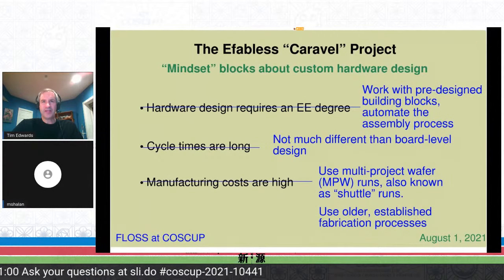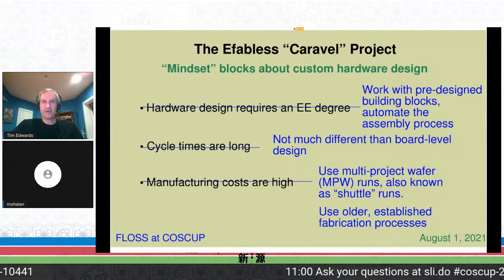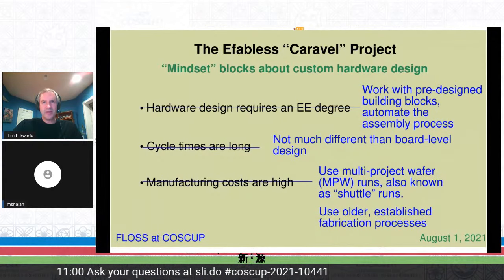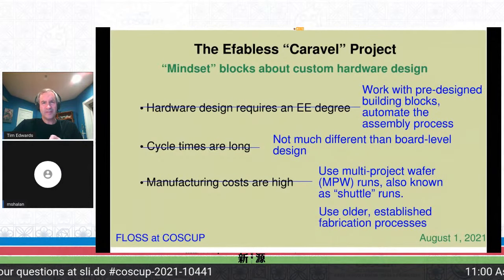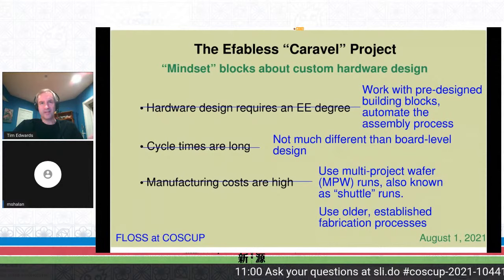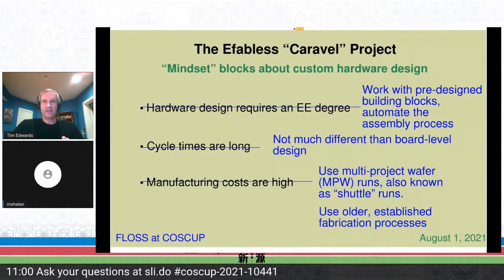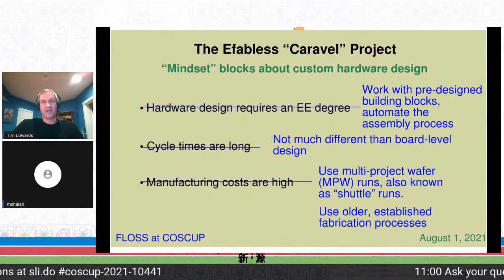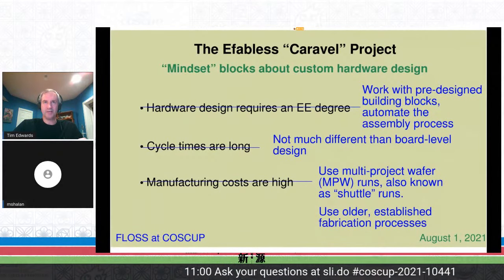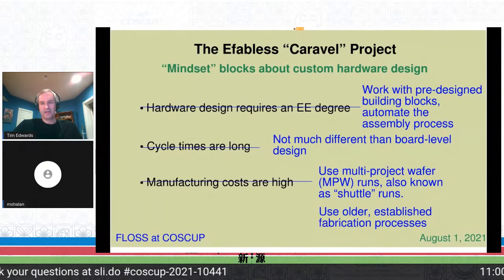As for the expectation that chip design requires PhD level knowledge and experience, it's really just a matter of having experienced people create a set of building blocks and a set of tools for assembling those building blocks. Generally speaking, it can be that simple. It's not trivially simple, but as long as the building blocks work as advertised, then the problem is mostly one of interfacing. And software developers know a lot about interfacing between one software package and another. In chip design, there are additional considerations like managing voltage domains, current density limits, ESD protection, power dissipation, but many of those can be handled automatically, even if that requires overly conservative design practices.